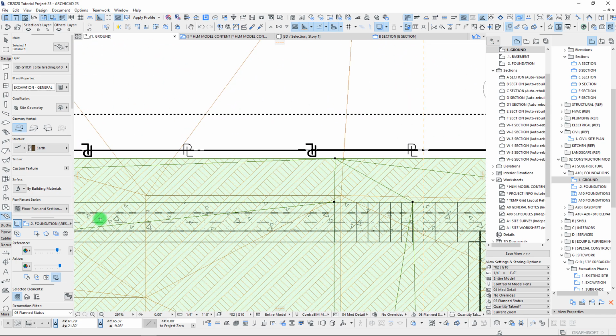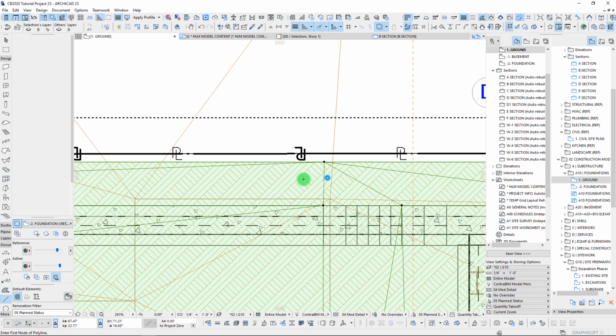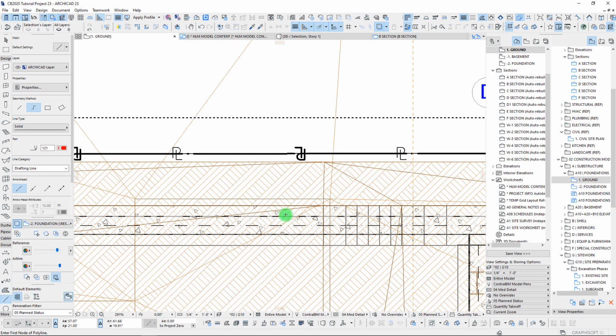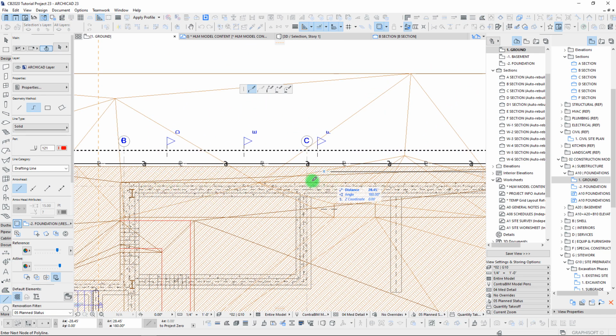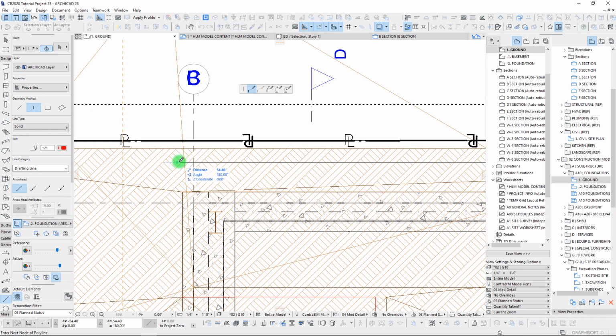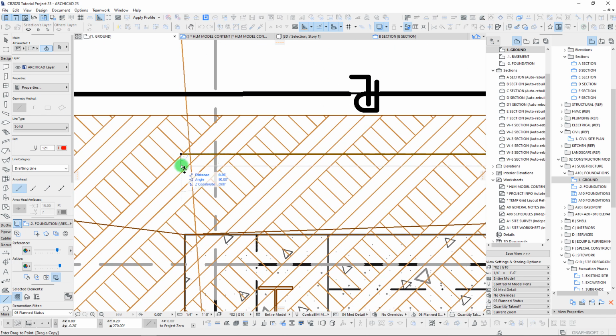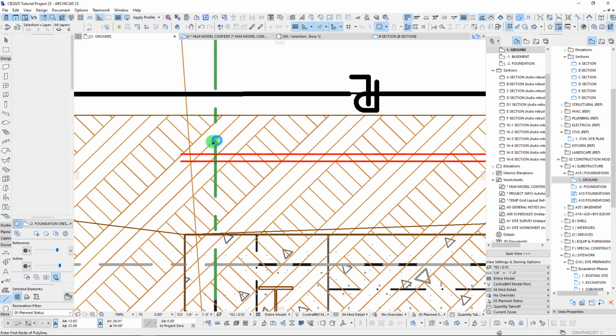essentially we just create two lines that are very close to each other. Say from right here, we can take a line, cut it entirely down this entire path. And if we wanted to create a step, I would create one here, and I'm just going to offset it just a slight amount here. And we select our mesh,